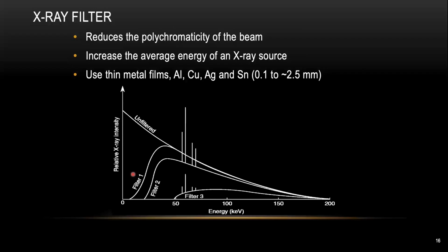The low-energy X-rays are not going to penetrate through the sample, but they pile up on the surface and create some kind of ring effect. So in that case, we need to implement some kind of filter to filter out the low-energy X-rays.